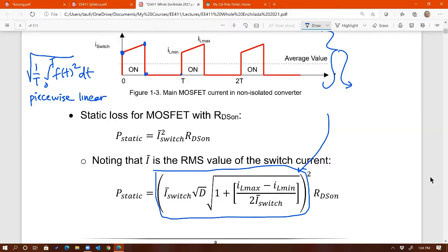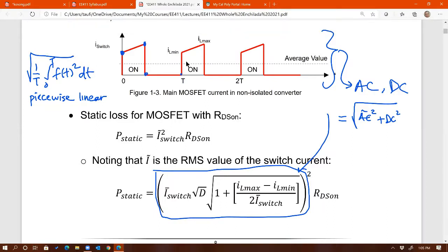All right. So this waveform, the red current waveform that you see here, is not flat, right? Neither is it sinusoidal. So anytime it is neither ideal DC nor ideal sinusoidal, that means the waveform has both AC and DC components. Therefore, total RMS would be the square root of the AC component squared plus the DC component squared. Remember that? Yes, remember this.